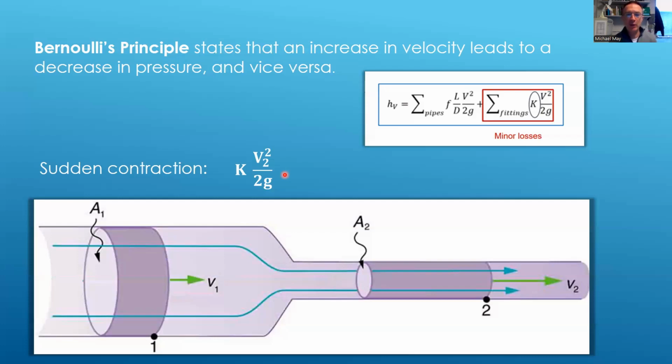So if you have a pipe network and you work out all the losses associated to that pipe network, you can then specify a pump big enough to overcome those losses and provide a pressure and a flow rate at the end of it to do what you want it to do. If you underestimate those losses, then that pump may not be able to do what you expect it to do at the end of that pipe network. So that's why we always err towards the greater loss. So you take V2 in this case, in this sudden contraction situation.